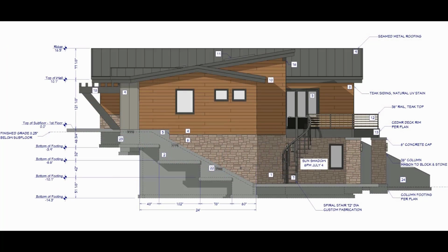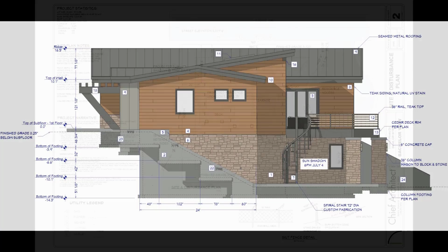If I show you the finished view that I've created, here's the way I've used the annotation to call out not only the dimensions, but you can see in my text where the terrain is at the subfloor level in the front, and then as you can see it transition and slope. I did that by toggling on the layer for the terrain and just using the CAD line and tracing over the top of it.